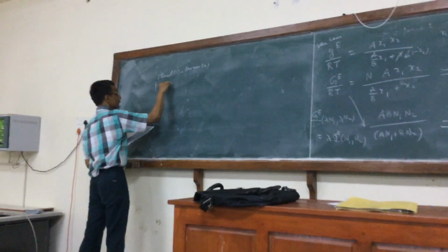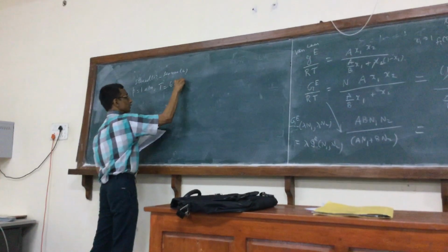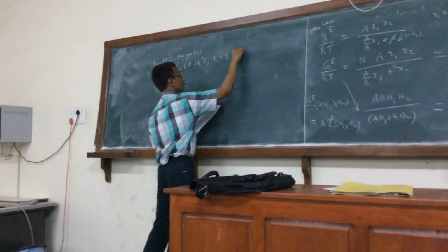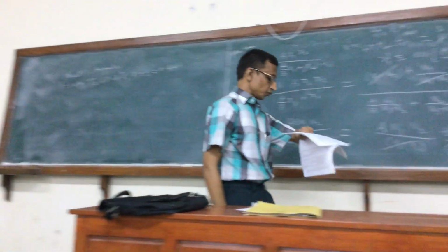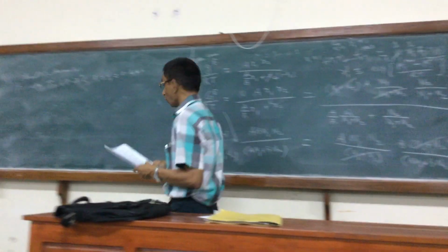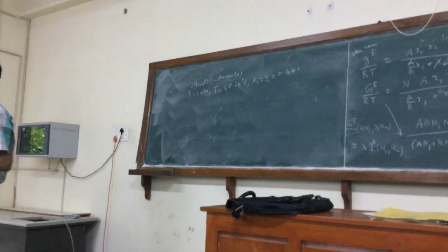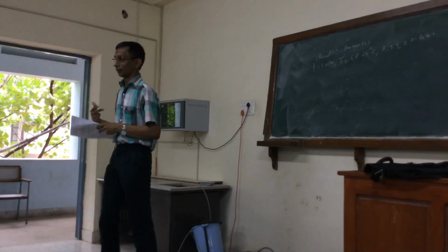The azeotrope is at 1 atmosphere. The azeotropic composition is 0.44 mole fraction of ethanol. This is where the azeotrope occurs. Now, how are we going to use this to find the parameters in any model? We get expressions or values for the gammas.